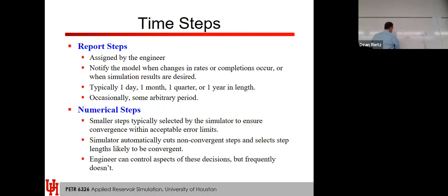So let me just say one thing. You could, by the way, plot time steps, and this might be 30 days or something like this, and this is in days. Let's say it's a monthly model. You could do this and then find the point where all of a sudden it drops to near nothing, and then it'll get back up again. So you can see if your model takes, let's say, 5 hours to run, but you're thinking, well, wait a minute, it's trucking along fine. Well, you might look at this and find that 3 of the 5 hours are 1 week of time. So then you can go back and do something to fix that.